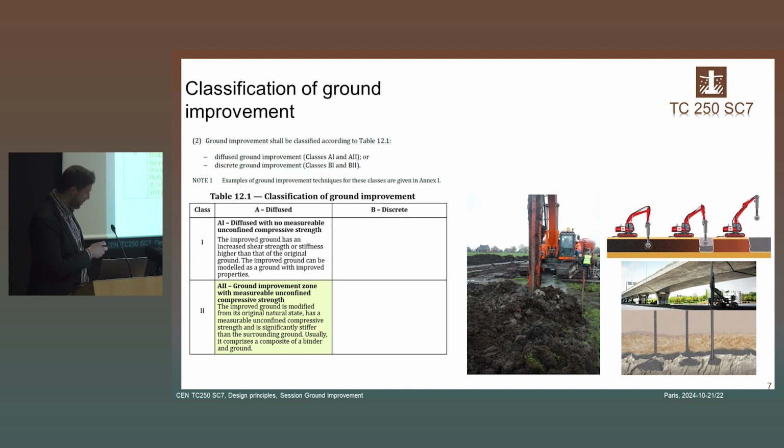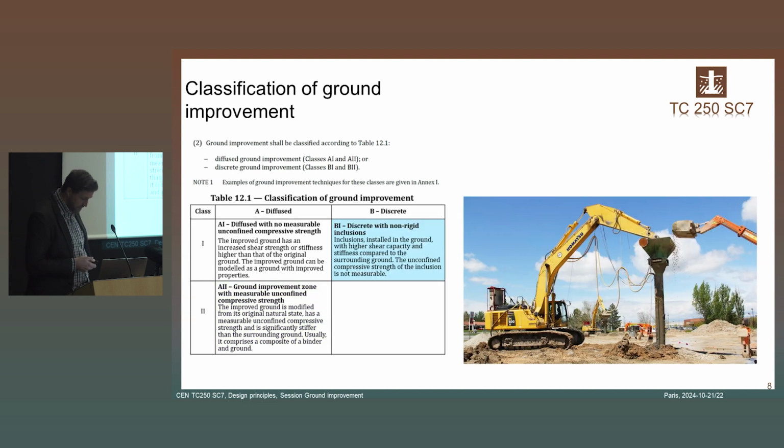If I correctly remember, we have 5 meters of peat soil, and this peat soil was treated with a global mass stabilization process, mixing the peat soil with a hydraulic binder, and at the end of the process, after hardening of the soil cement or soil lime mixture, we can define a UCS value for this global mass, which has been stabilized.